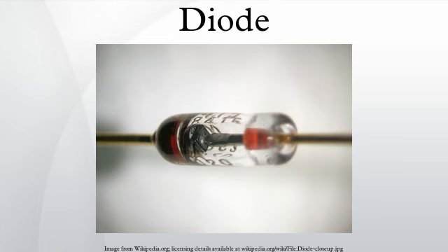A block of N-type semiconductor is built, and a conducting sharp point contact made with some group 3 metal is placed in contact with the semiconductor. Some metal migrates into the semiconductor to make a small region of P-type semiconductor near the contact. The long popular 1N34 germanium version is still used in radio receivers as a detector and occasionally in specialized analog electronics.